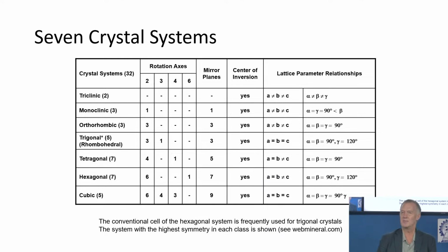All right, so talking about crystal systems, we need to define all 7 of our crystal systems. Here they are in definition. These are the lattice parameters, and you'll have access to all these slides, of course. So cubic: a equals b equals c, and alpha, beta, gamma are all 90 degrees. For triclinic, a, b, c don't equal each other, and alpha, beta, gamma don't equal each other, and they aren't 90 degrees. So, definition.